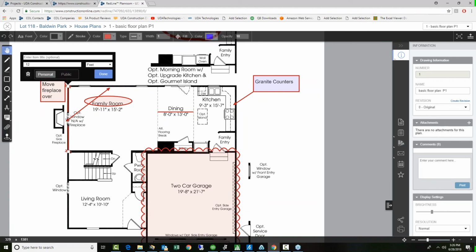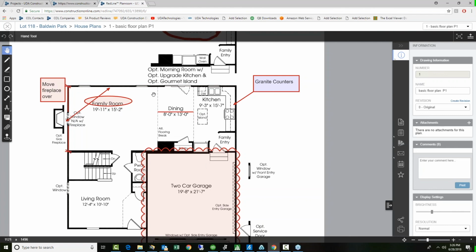And then you can apply the additional measurement in this area. So let's just say that this is about 15 feet. This is about a 15-foot wide room. This just sets the scale for the drawing. So now, in addition to being able to calibrate this and draw some of the boxes and everything like that, we also have some options here for measuring lengths or calculating areas for rooms as well.